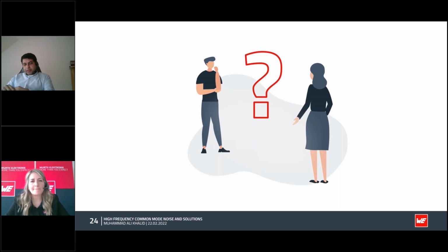It's not recommended to use them in combination because a filter is still an extra device on your data line, which also affects the data line signal. And with one filter, we can ensure that the amount of losses are within the limits of what we are showing in the data sheet. So that's why it's always recommended to use just one filter on one data line and to be sure that your data signal remains untouched, or is as intended.